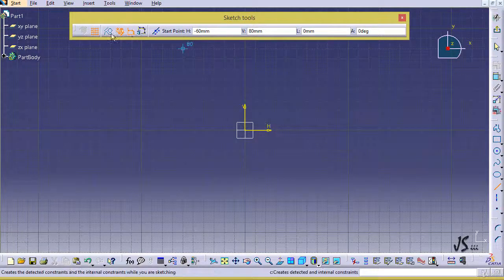One of them is snapping to the point. Right now snapping is enabled, so you can see that when I am moving my cursor, it snaps to the grid lines, as a matter of fact, the intersections of the grid lines. I can disable or enable the grid just by typing grid command in the text box. Right now, it should be there. It is not going to hurt.